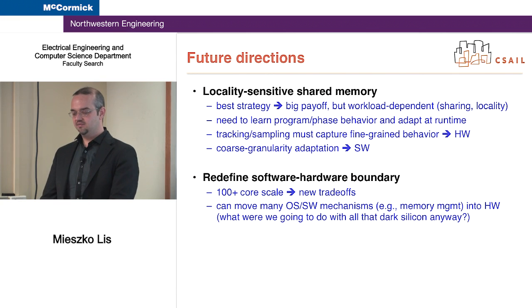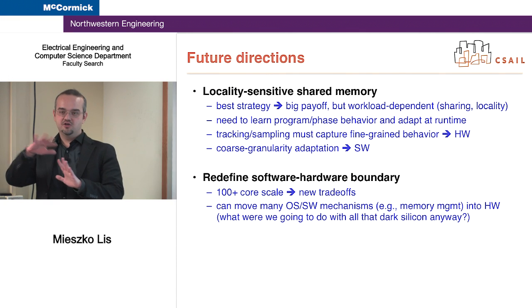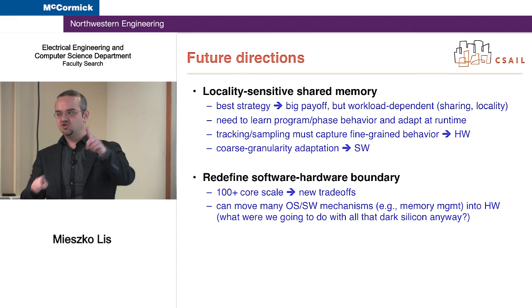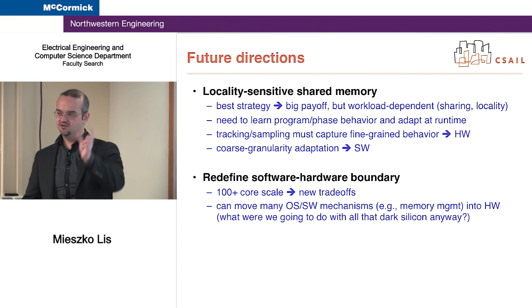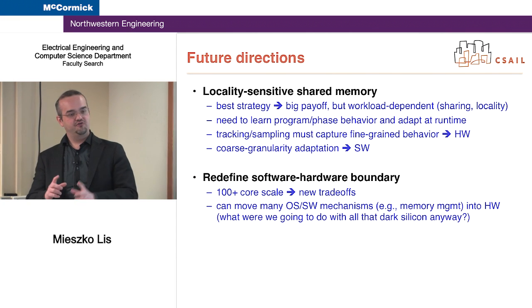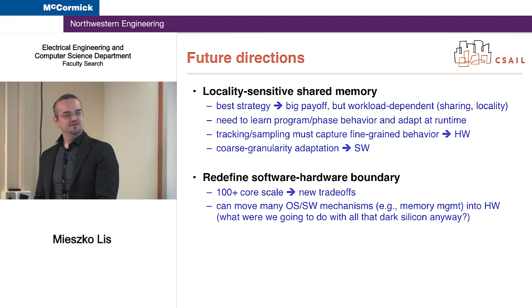The reason it works, incidentally, I think, is that once you get to 100 cores, about that level, the trade-offs become different, right? Because the on-chip distances become longer, effectively, in terms of number of hops. Things that work for 4 cores or 16 cores, where you can even have a bus maybe, work really well.